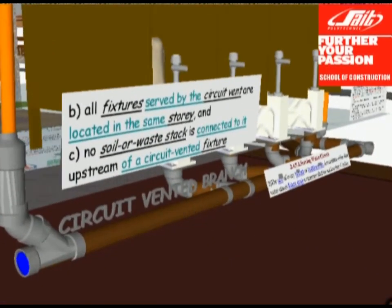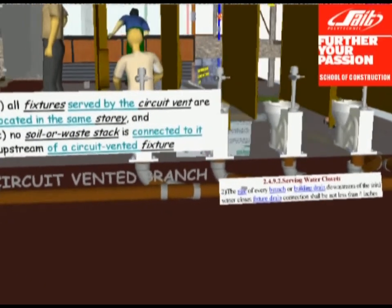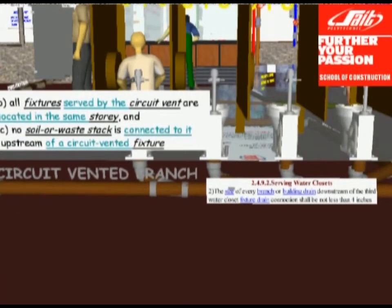This clause tells us that all fixtures must be on the same story to be circuit vented. Also, no upstream soil or waste stack can dump into the circuit vented branch. Clause 2492 Section 2 tells us that after the 3rd toilet, every branch or building drain must be 4 inches in size.